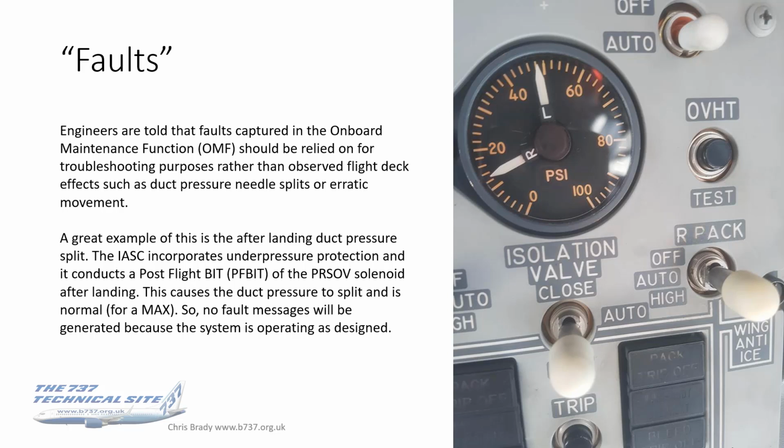So no fault messages will be generated because the system is operating as designed, but you as the crew will see this duct pressure split. In fact, you'll see it flapping around several times while it conducts this BITE check on this component.